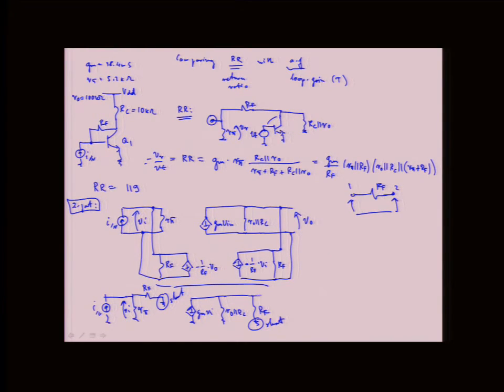So then this would be your VO here. And you would use this circuit to calculate A. You can do exactly the same thing from the top circuit, right? The way you calculate A is you would obviously disable the feedback, and then calculate A.